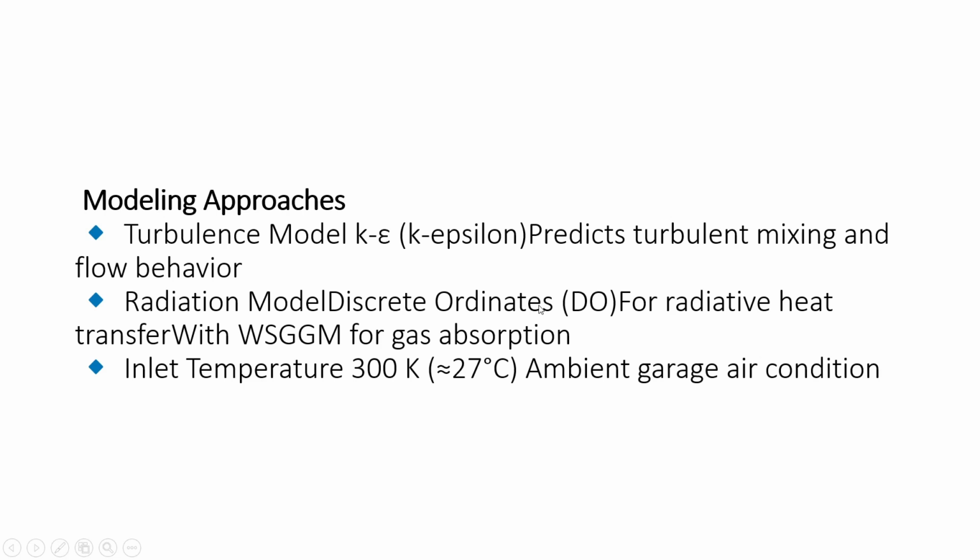Radiation model: discrete ordinates, DO, with WSGGM. For the radiation heat transfer, we apply the DO model, which calculates radiative energy exchange between surfaces and gases. The weighted sum of gray gases model, WSGGM, is used to approximate gas absorption behavior, especially important for high-temperature gases.